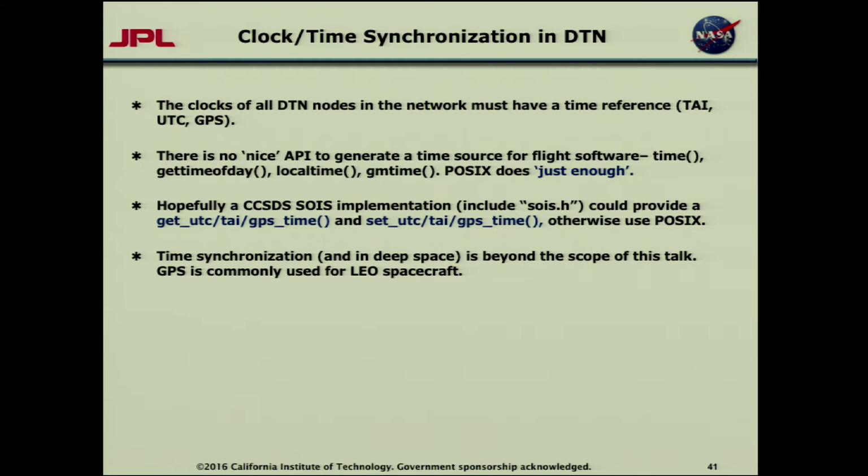This is beyond the scope of this talk, but time presents its own challenges because you have various types of time: atomic time, UTC, GPS. There is no nice API that just generates a time source for flight software. I mean, you have POSIX, but POSIX does just enough, and then you have to start to look at what we have implemented within our own framework.